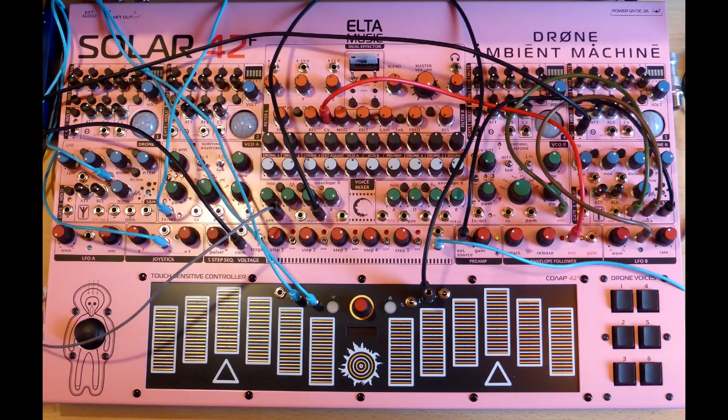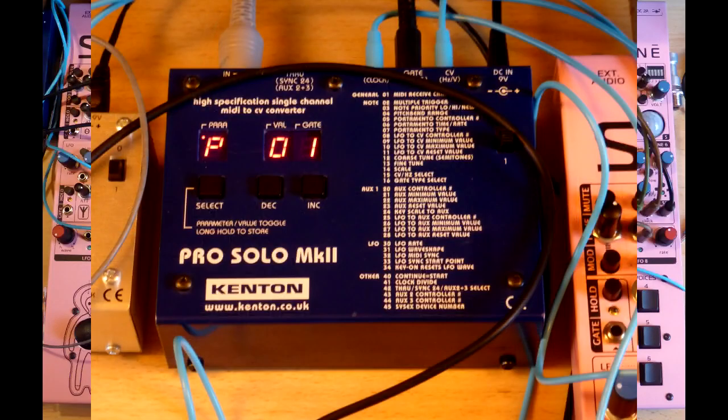Now we come to gotcha number 3 when you try and play it back. Now with the live performance, the Solar keyboard drives VCO-A using CV and gate signals. But you guessed it, the Solar VCOs need a gate of at least 6.7 volts to trigger them, so the MPC gate is obviously too low. But why not switch to MIDI playback into the Pro Solo converter and use its CV and gate outputs instead?